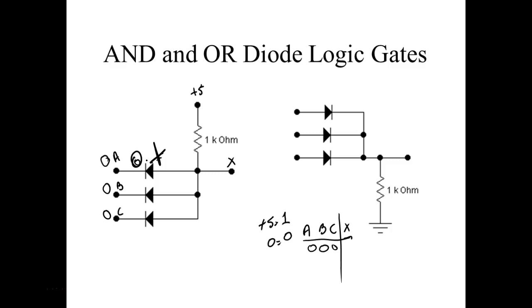Okay. Hold on, see. So is it forward biased? Is the anode positive in respect to the cathode? Yes. Here's the anode. I got a positive sign on the anode. There's that 5 volts up there, right? Pointing toward here, right? This is 0 volts, it's not no voltage, it's 0 volts. There's a big difference between no voltage and 0 volts.